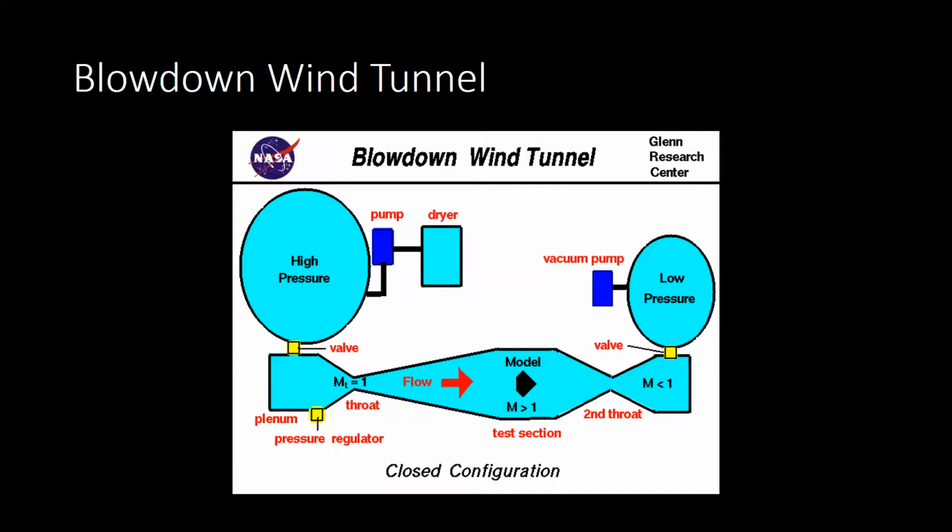At least in the case of air, this happens around maybe Mach 4 or Mach 5. But this heater right here, or dryer, can help keep the air above the liquefaction point. This issue arises even further when you're talking about Mach 20, because at higher speeds, it becomes very difficult to reach the increased temperature needed to keep the air from liquefying. At lower Mach numbers, you have to increase the air temperature by a small amount, but as you go faster and faster, you're going to have to increase this temperature more and more.